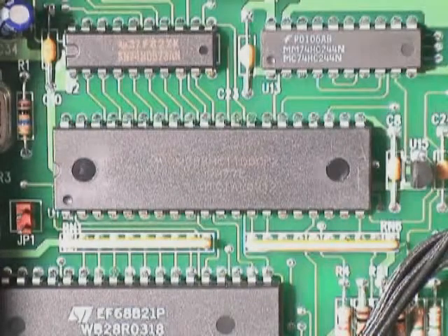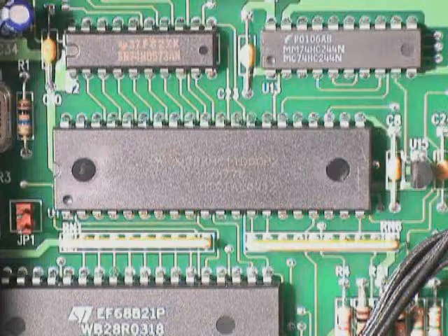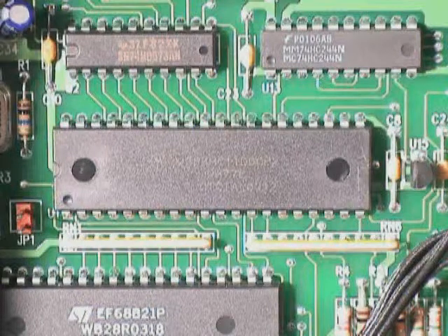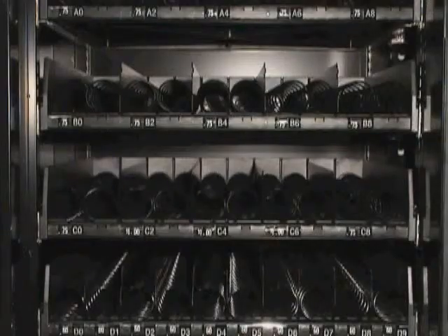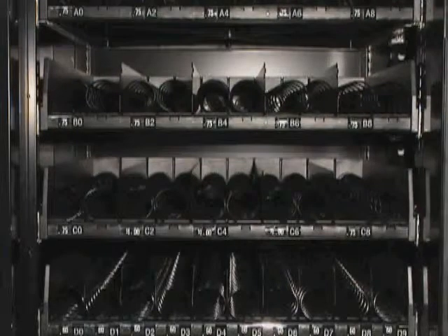Most microcomputer systems use a concept known as the matrix to control, or be controlled by, various peripheral devices. Keypads, displays, and even the tray system in the snack merchandisers, as well as applications for other merchandisers, are all examples of matrix devices. A matrix can be pictured as a grid with vertical and horizontal lines that intersect in a symmetrical pattern. The points where the lines cross represent an input, such as switches, or an output, such as motors or digits in a display, to the microcomputer.